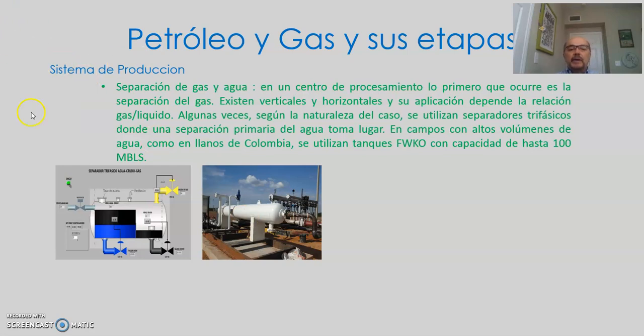The separator did a good job. The water we separated here had a quality equivalent to less than 100 parts per million of oil. If we compare this to what we were getting with the feed water knockout installed in the CPF with 100,000 barrel capacity at 5-hour retention time, so 500,000 barrels being handled for that tank, that was a huge tank.